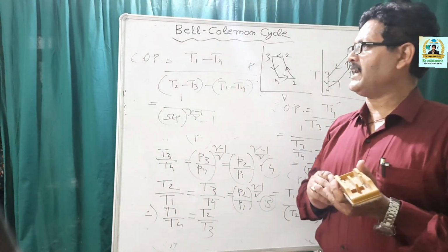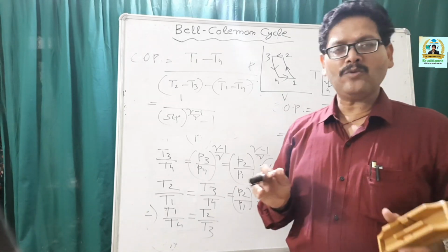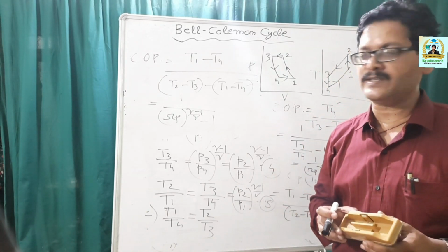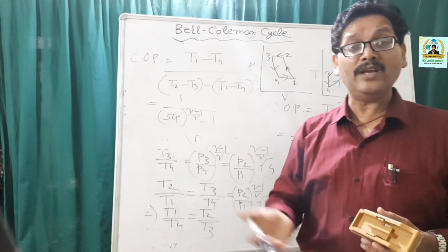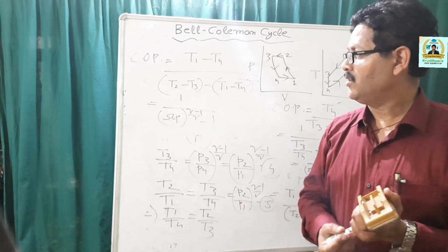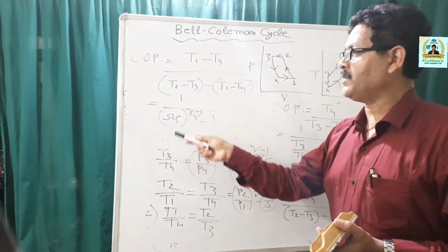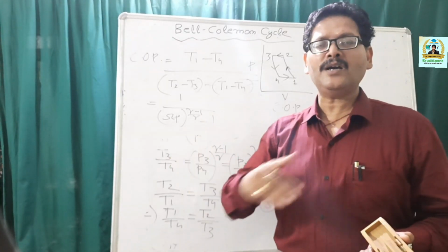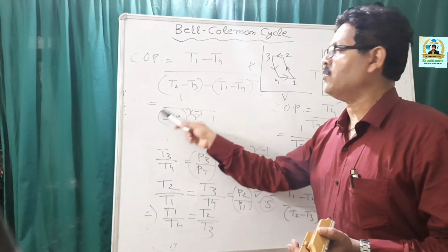One thing that I have told you at the beginning, that by going for the closed air refrigeration system, you can maintain minimum pressure at a higher value. So if you maintain a pressure at a higher value, the C.O.P. will improve. That can be observed because higher will be the minimum pressure, lower will be this value.